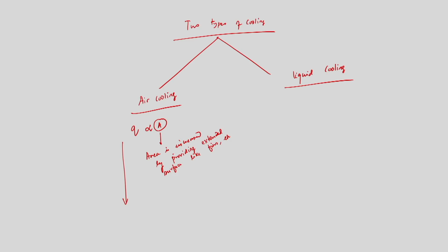Now, another important point in cooling: apart from the forward motion of the engine allowing air to come in, sometimes a blower is provided. Sometimes a blower is used to increase the rate at which air is supplied. The blower is used to increase the mass flow rate of air.